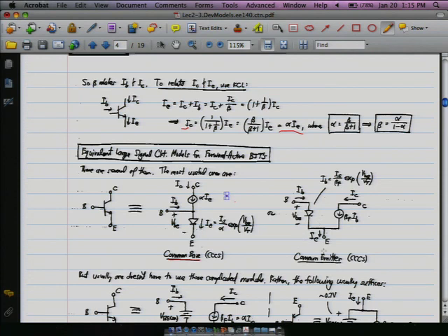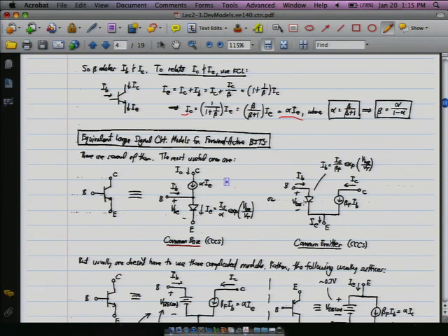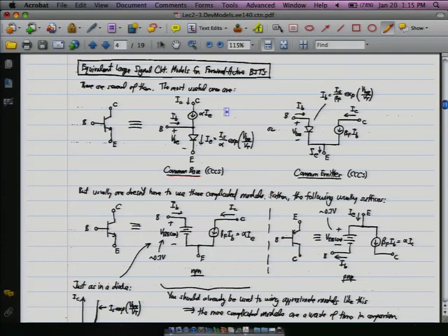And that's what I was drawing up here earlier on the board. In this case, the reference is this ground node. This is the small signal ground in the circuit. In the common base case, the base becomes the small signal ground. So you just have to be aware of which model you're using when you sketch it out. But it comes out to something very similar. Again, we have this current over here that's beta IB. Again, that's just IC, the collector current, and we have this diode. It's just a different way of representing it depending on what your focus and goal is.